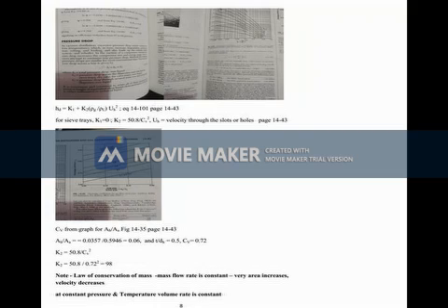FLG, and here you assume a tray spacing of 450 mm, which will be safe. From the tray spacing of 450 mm, from figure 1431 on page 1438, a plot, you can see that FLG is plotted against some parameter, CSB. Here for FLG of 0.054 and 450 mm tray spacing, find the value on the y-axis, that is CSB equal to 0.088 meter per second.